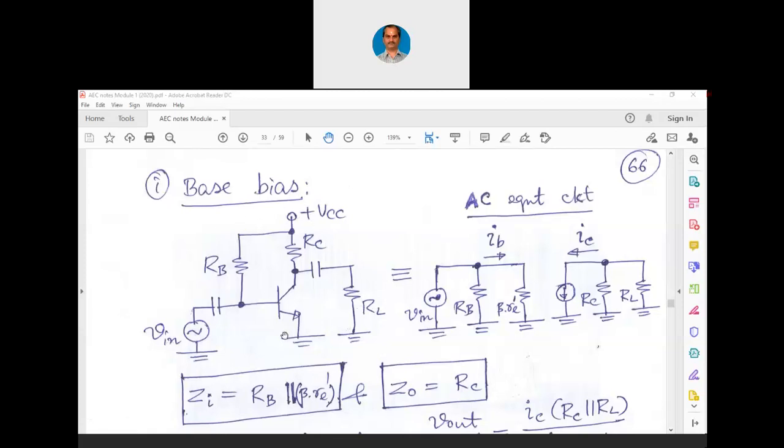What we do now is, we represent this transistor by means of this pi model. You can see this here. The emitter is grounded. At the input, I have this beta into Re, which is the dynamic emitter resistance multiplied by beta. And at the output, at the collector, we have this IC. This IC is nothing but the collector current, which is constant around the Q point. So the complete transistor, we have written using this pi model.